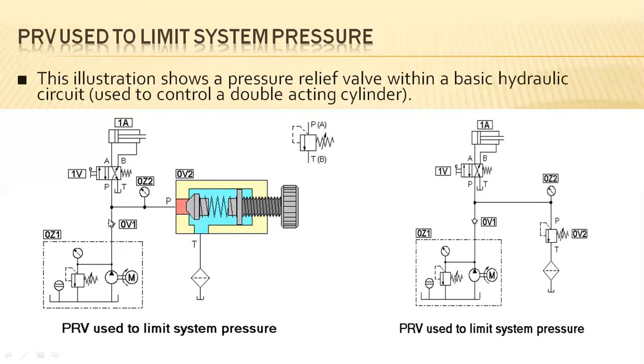Before entering here, there is a check valve over here, and before entering the directional control valve, it is verified by this pressure relief valve, because the system suddenly has to be decreased by 1 bar of pressure to be operated, due to the environmental conditions in external situations that have to limit the pressure. So at the inlet condition, already 1 bar of pressure has been limited. So it is impossible to limit the pressure after crossing this DCV.